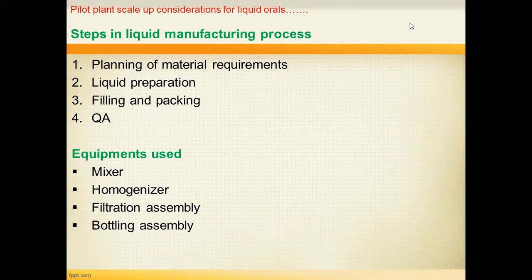In the case of a solution, you can consider the tank diameter during the mixing process, which type of impellers you have to implement, its diameter, rotational speed, number and mixing capacity of the impeller, number of baffles, and the clearances between the baffles. These are all the mixing assemblies used in the preparation of a solution, and they have an impact on the